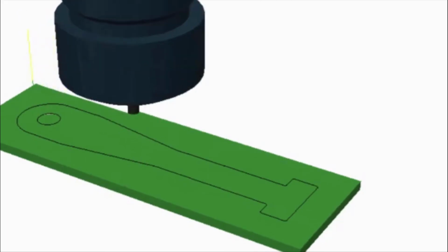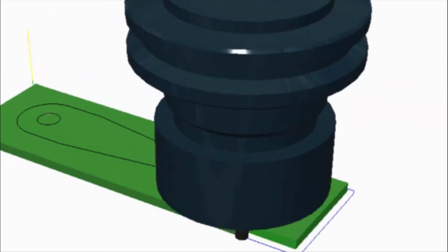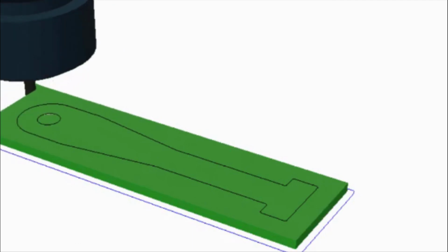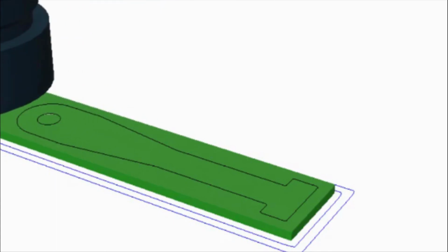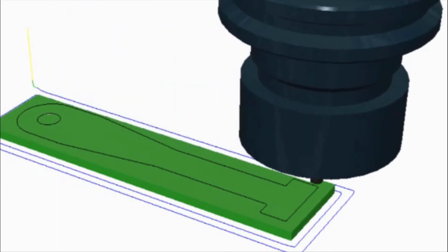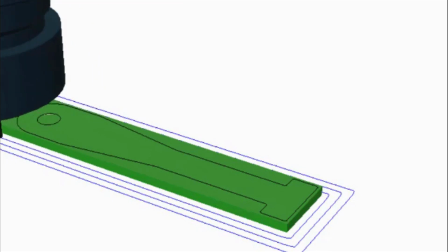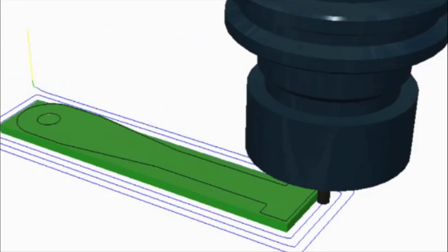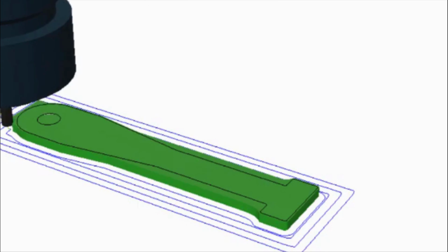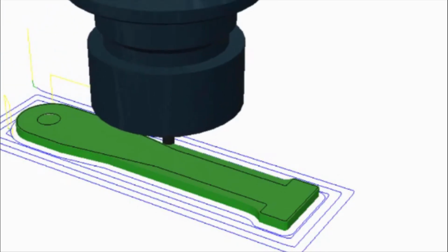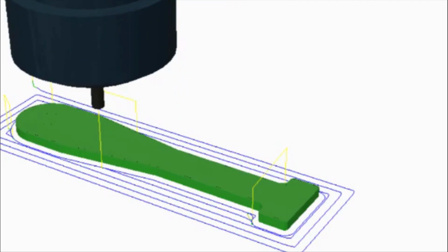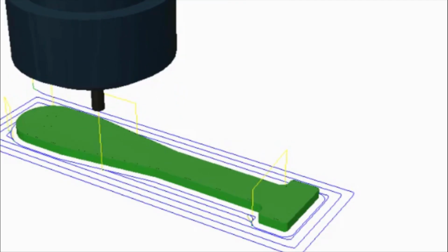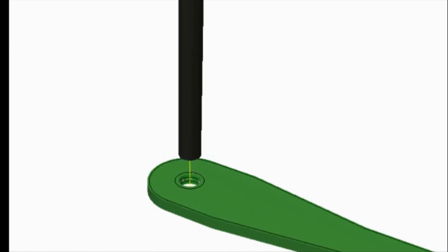Now that we're the correct thickness, we can begin to make the cutout of the rough shape. You'll want to switch to a much smaller end mill so you can more precisely match the boundary of outlines you made initially. You are likely going to be able to get this outline closer and cleaner than you would be able to with the bandsaw, though it will take more time. Once that's done, we can now drill the holes in the exact same fashion as we did before.